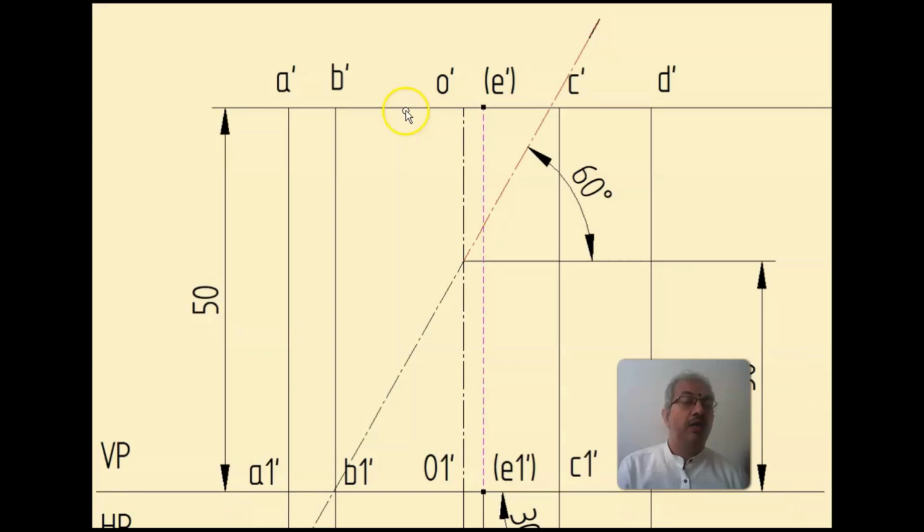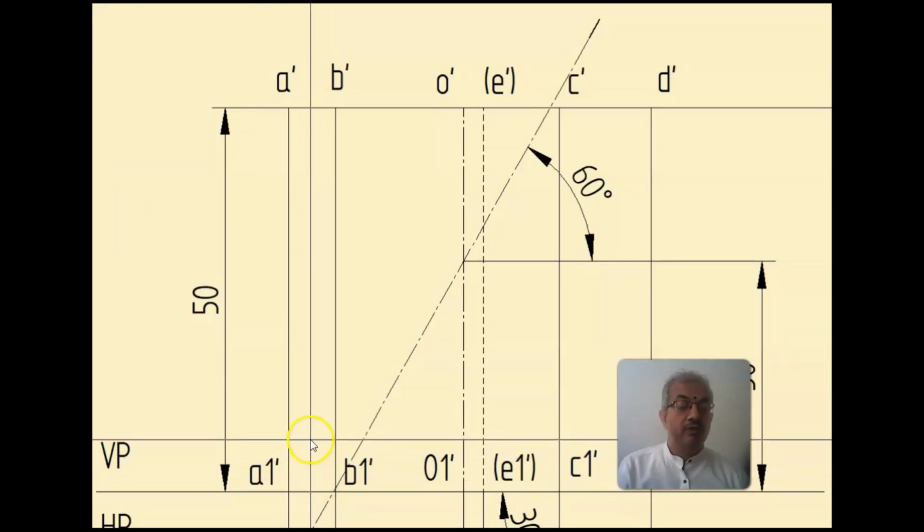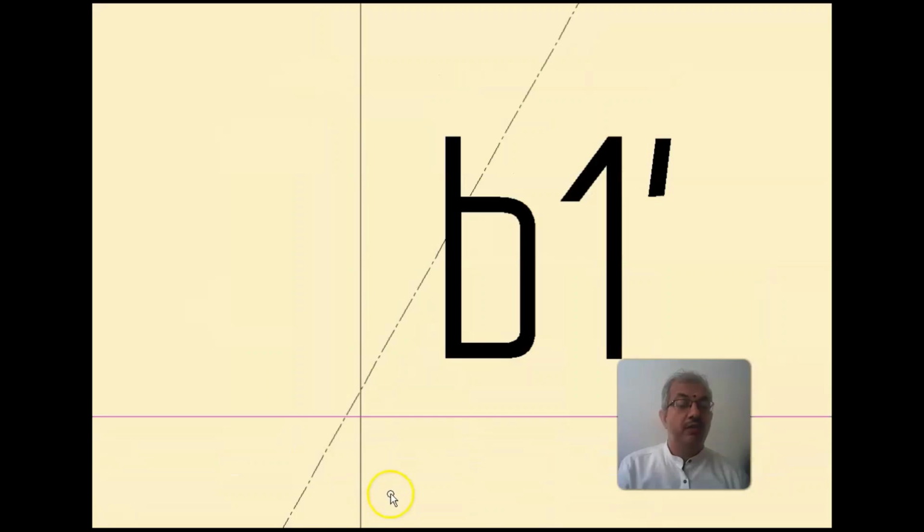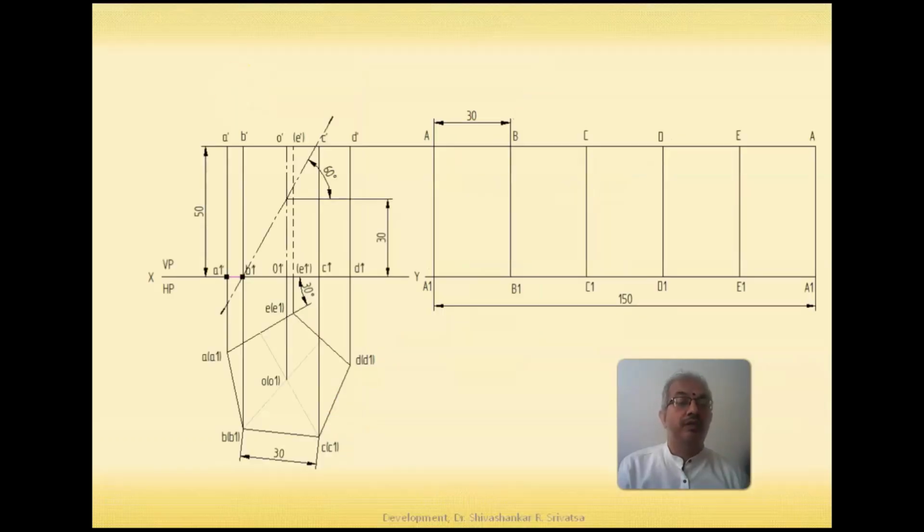So, and in addition to that, now if you look at the top face here, the top face is cut by the plane over here. And similarly, if you look at the base of the object, the base is also cut. Now if we observe close towards this point over here, we can see that this is the edge BB1. BB1 is also cut, and some part of this base is also cut by the plane.